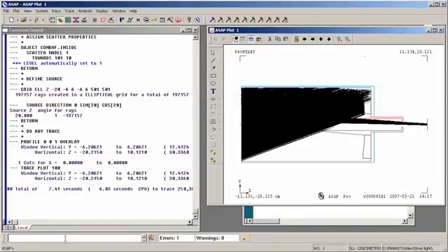If we want to actually see the distribution of light on the detector, we have to ask for it. We tell ASAP that we're only interested in the light on the detector. Consider only detector. We want a window whose vertical axis is Y and horizontal axis is X. And we'll set up the resolution for our calculation. I'll say 15.